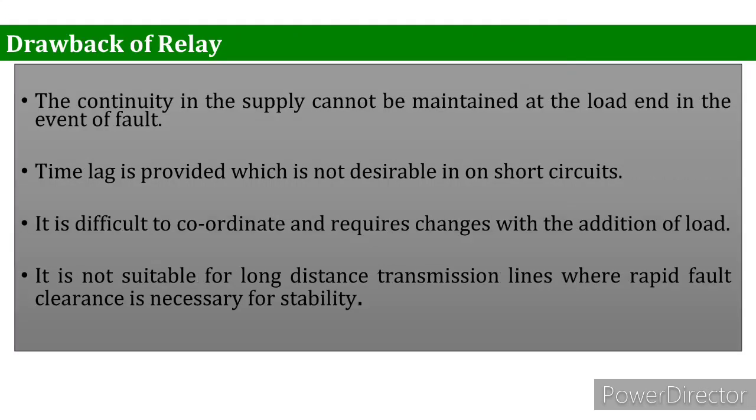There are some drawbacks also. A few of them I'm mentioning. The continuity in the supply cannot be maintained at the load end in the event of a fault. A time lag is provided, which is not desirable on short circuits. Along with that, it is difficult to coordinate and requires changes with the addition of load.